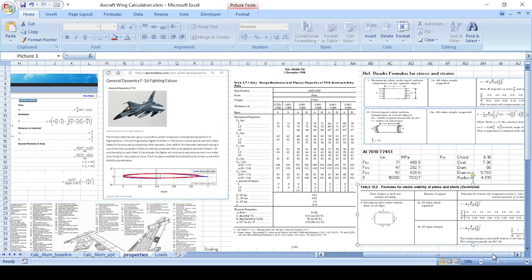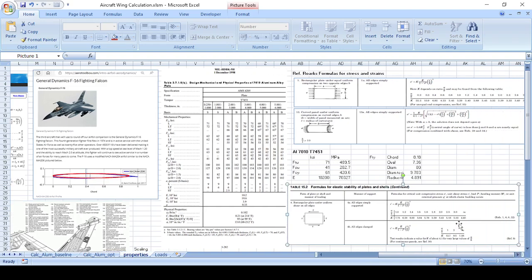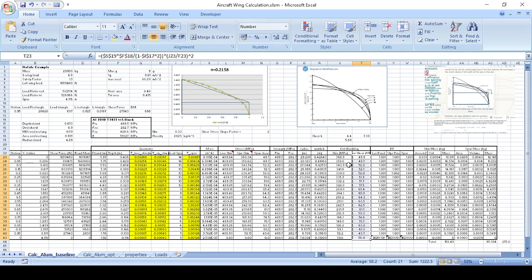Now for the equation here, what you'll see is that I've used this infinite number of 4.4 for the simply supported and 7.8 for the clamped. Now in my section, this is conservative. I believe in this case I may have used an average of the two, because I could be simply supported. I could use the 4.4 or use the average of that, and I'll just put this number there. Anyway, just an exercise for you: you can put that number there to get a different thickness.